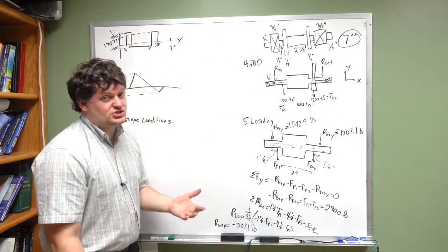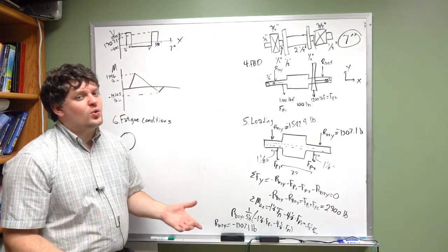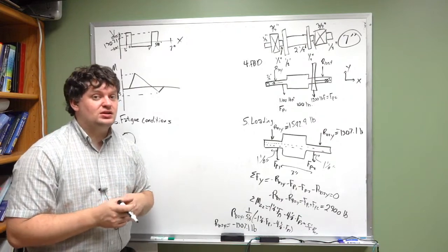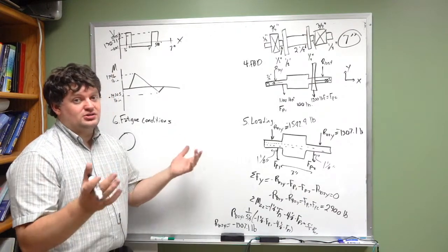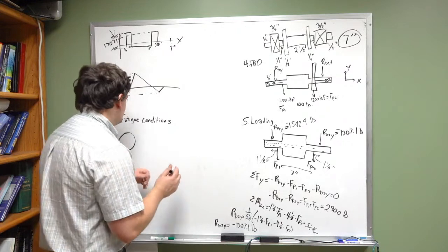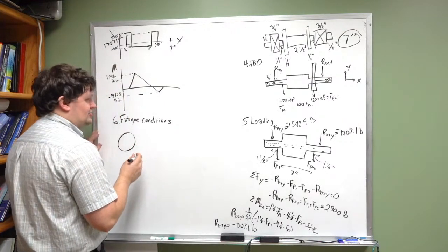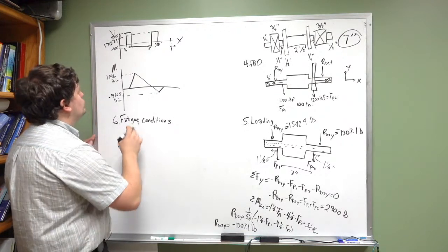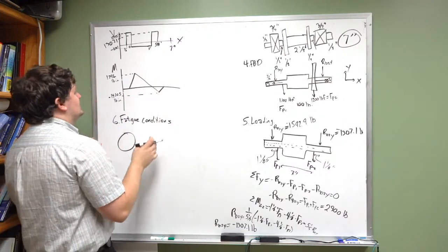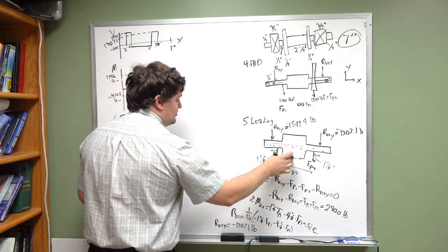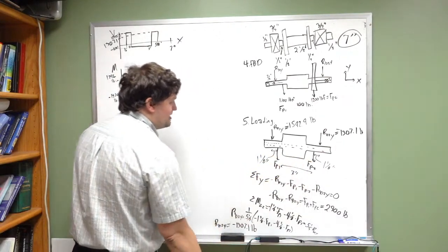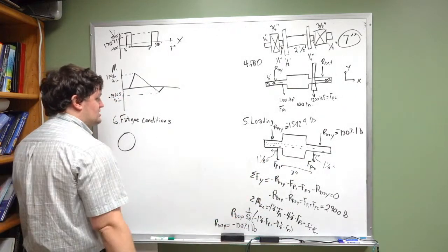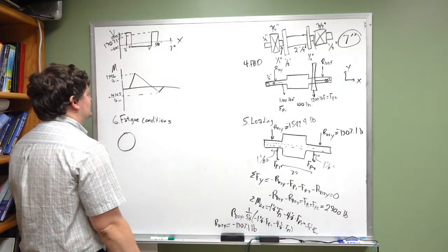Since this is only a 7-inch shaft, there's not a whole lot of benefit to making this hollow. So we might as well make it solid. That does save on calculations. Okay, so we're going to assume this is a solid shaft now with some kind of a step in the middle. The greatest moment load is found right here at the pulley, but then we have that moment load being carried across that stepped shaft. And we have that torsion being carried across that stepped shaft.